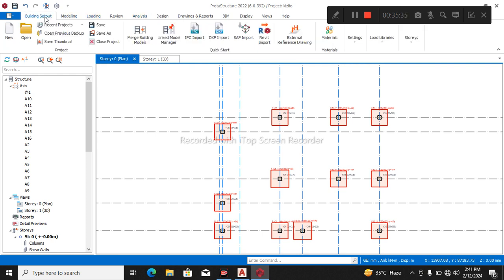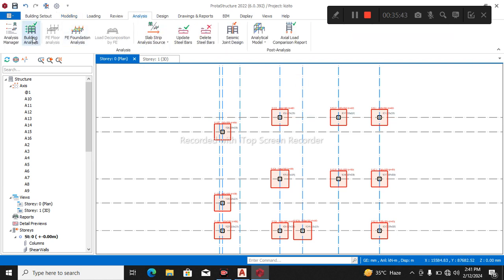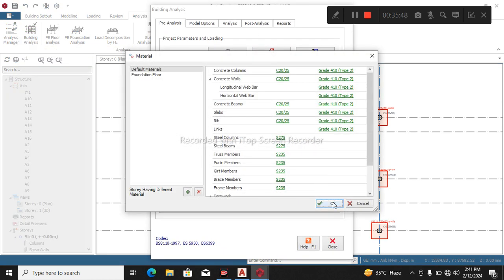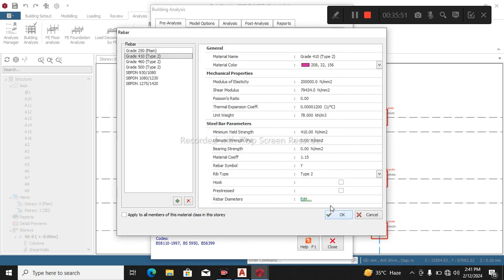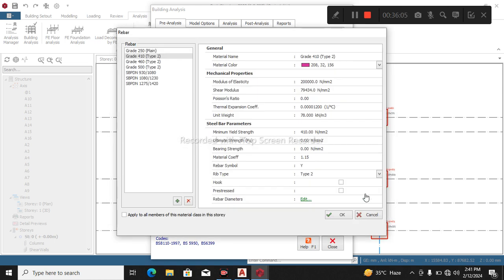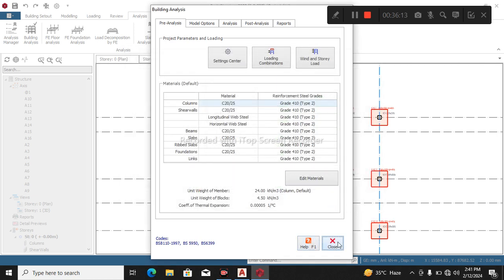within the column, your building setup. Because you're not supposed to show Y16 since now story building. You just come back to your analysis, come back to your building setup, come back to your edit design, click on this, go back to edit, see your foundation here. You can uncheck this 16, put 10 and 12. Why is it supposed to show 16 for foundation? 16 is too much for residential. 16 is too much for this thing. The software over designs sometimes.